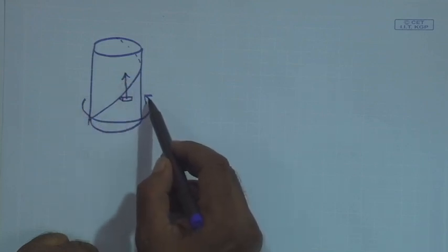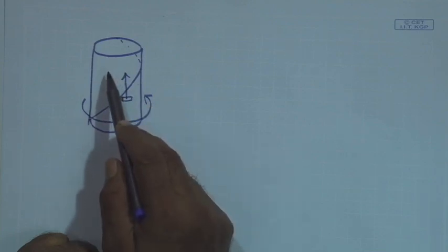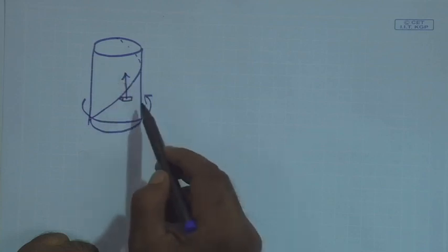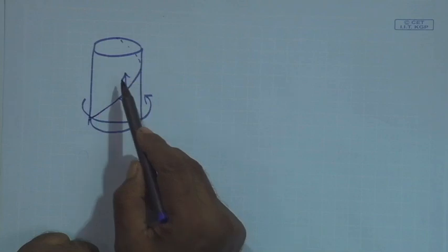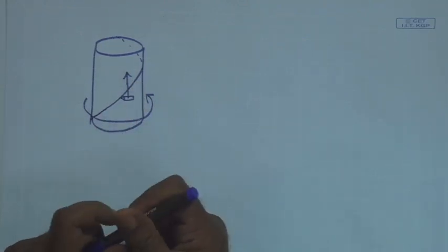and this particular proportionality is maintained, even though this might be slowing down. I mean, the rotation or translation might be slowing down. If they are proportional to each other, this will be describing a helix. This is the principle we are using for cutting out a helix in case of helical gear cutting.